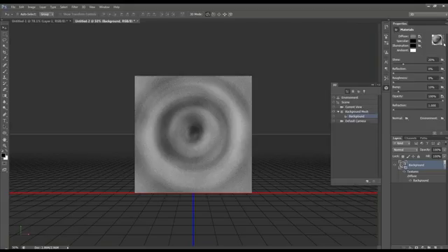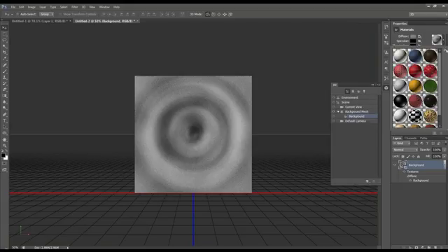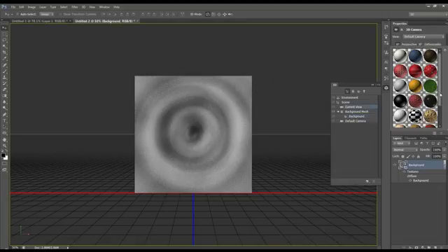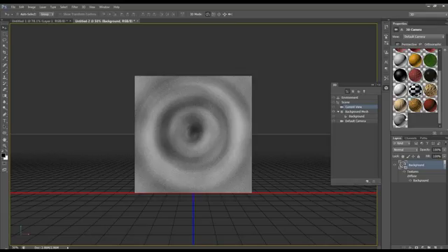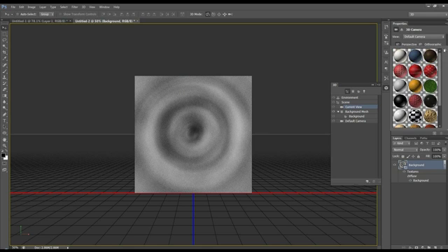And up here we're going to click on this little flyout, choose new material, and we'll just call this demo MT. Click OK, and now that material appears as the last material in your material options.